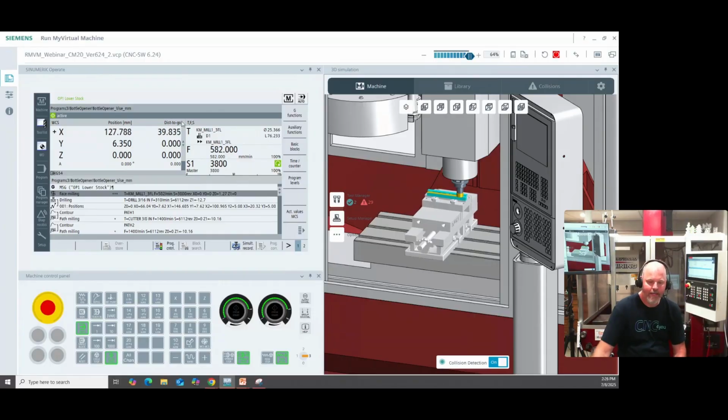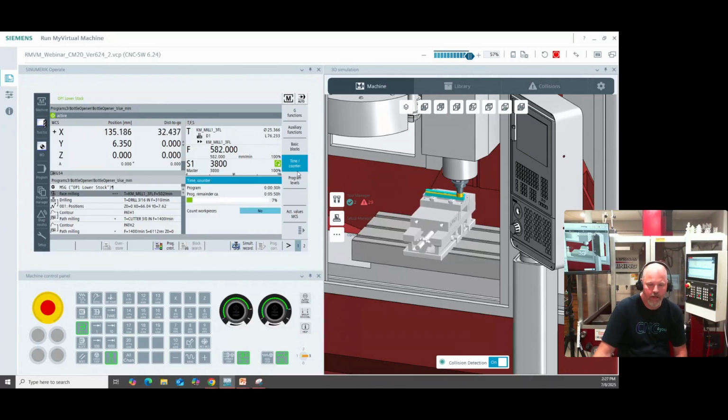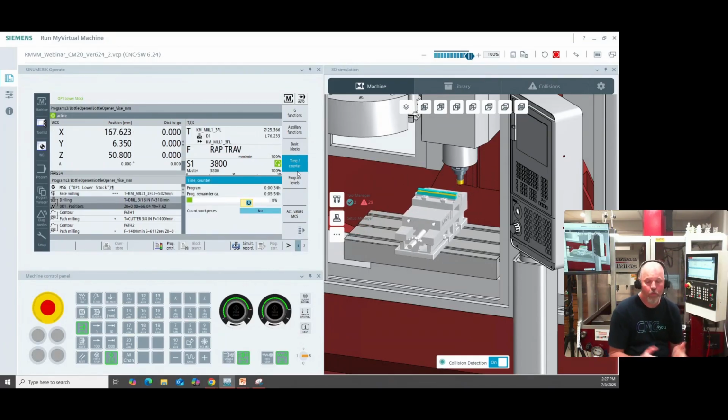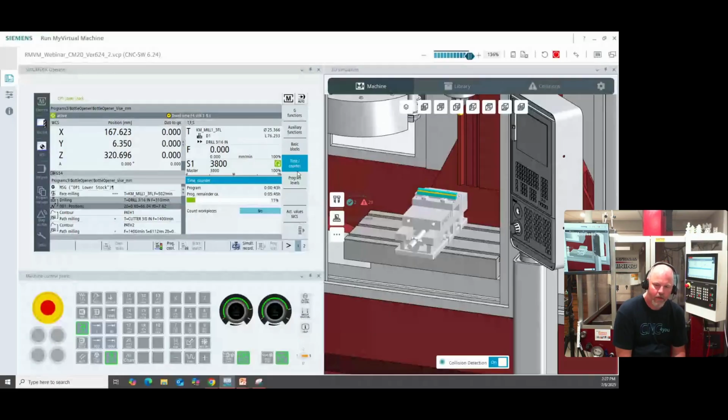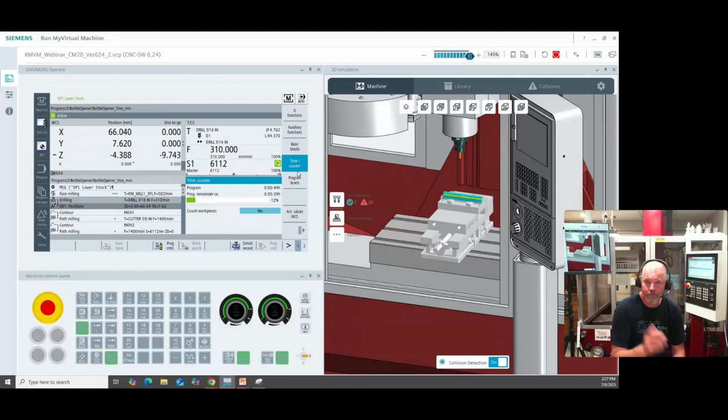Yeah, so at the end, what we'll do is we'll take a look at the cycle time counter, and that'll give me truly a one-to-one representation. Usually, that's the only area that may be slightly off. If I look at chip-to-chip time, in this case, that's not a servo turret, right? This machine behind me has what we call a Geneva drive on the tool mechanism.